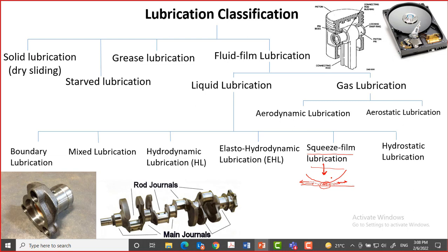But if we select a lubricant of sufficient viscosity, then the viscosity ensures that the lubricant will not be able to get out of this contact immediately. So there will be enough time during which the motion will reverse. Since it is in reciprocation, it can be because of vibration or it can be part of the design. So squeeze film action is always present in most of the bearings.